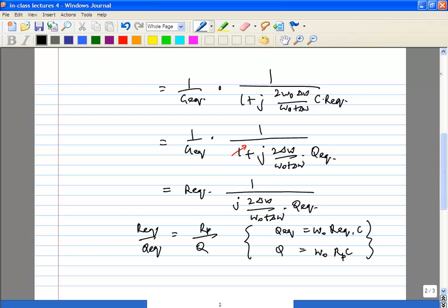Equivalent Q is large irrespective of the frequency. If you consider the frequency of oscillation, obviously there is no effective resistance; effective Q looks as if it's actually infinite because you don't have any parallel resistance at the frequency of oscillation. If you move just a little bit away, your Qs will be very high. You can calculate it out for a particular offset. The closer, the higher the Q, definitely.